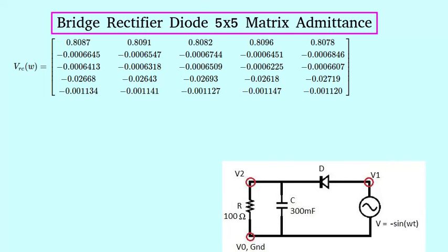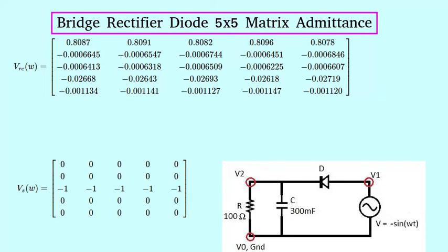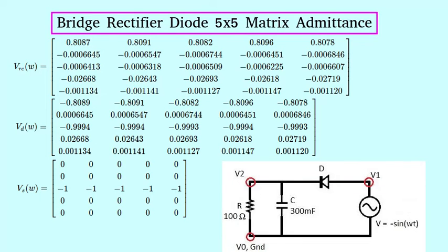And this is the matrix of sample load voltages for varying values of R and C. And this is the matrix of sample source voltages, which are all the same and only containing the sine function, with no DC voltage or AC voltages of other frequencies. And so this is the voltage across the diode, and we get this by adding these other 2 matrices together. Then we'll go through the same process of finding diode admittance for these values as we did for the diodes on the positive switching cycle. We'll need to have both of these matrices before we can do the next step.